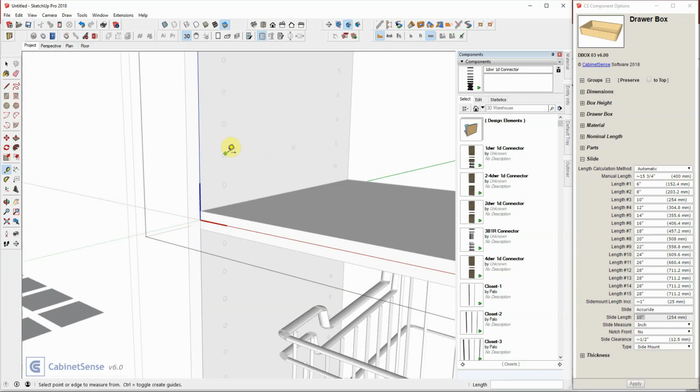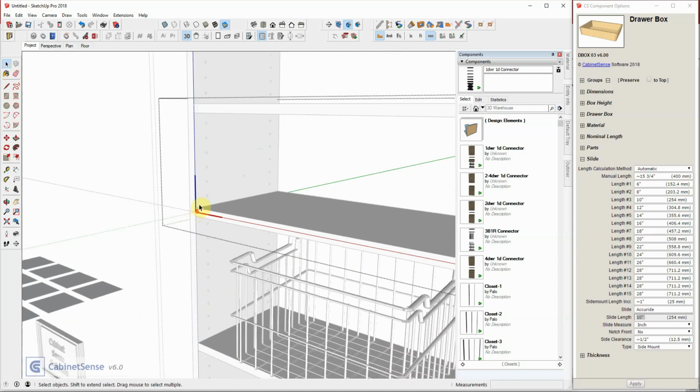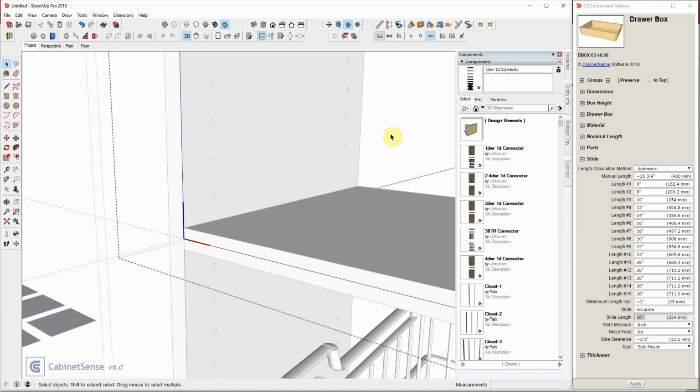If our slides could work, we could have specified this hole, and again, we wouldn't have drilled any extra hole. So it really depends on what slide you're using and if you can accomplish using all the holes in your line boring setup. That is our front to back drilling.